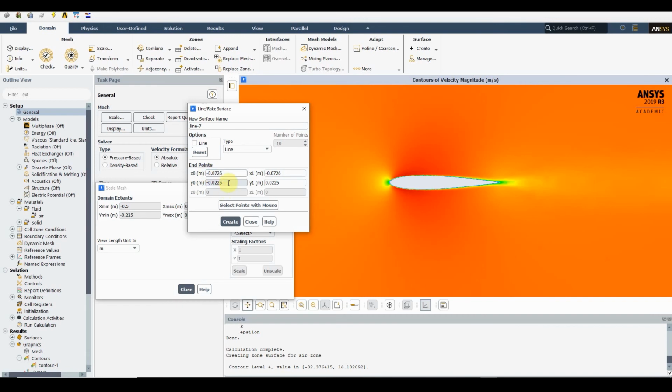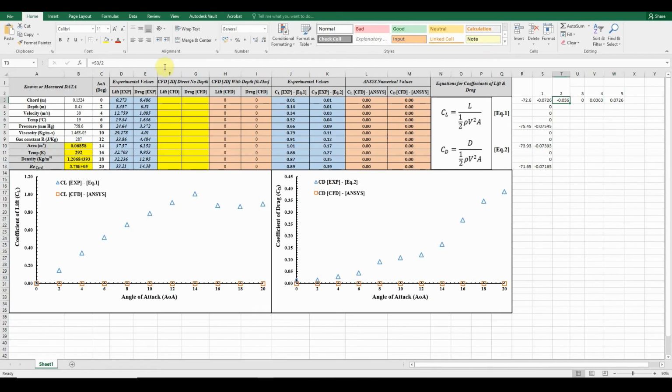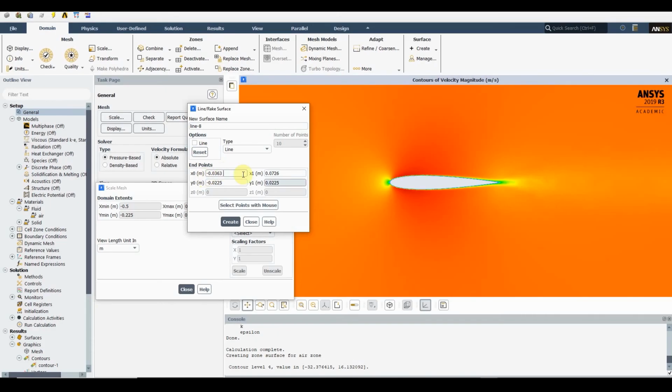So what you can do quickly, rather than rewriting it again, we know that this is P5. Create. Then Control C, Control V, this is P2. And then to get rid of the minus, get rid of the minus, and this is position 4, create, and 0, 0 is position 3, P3.